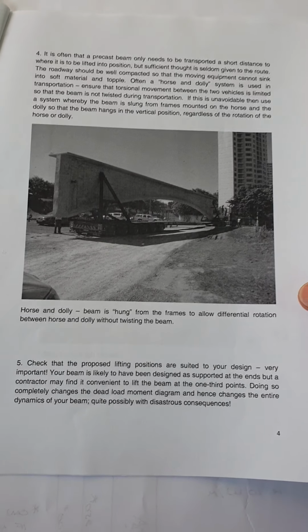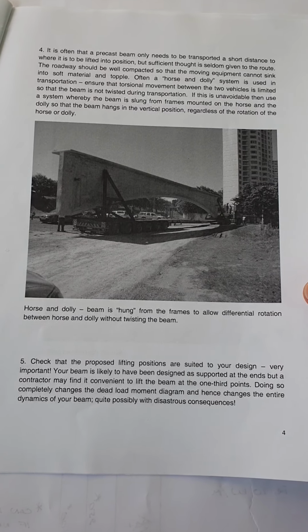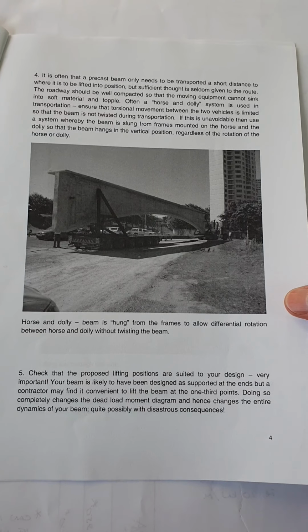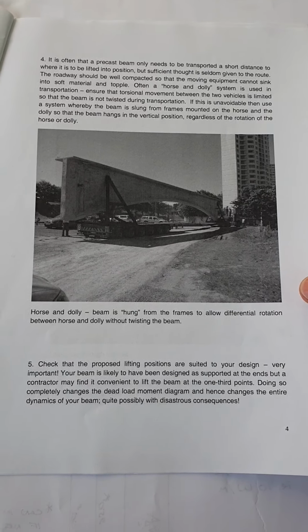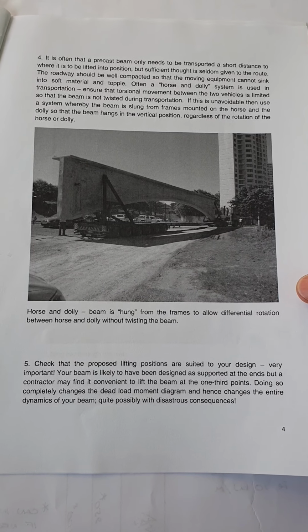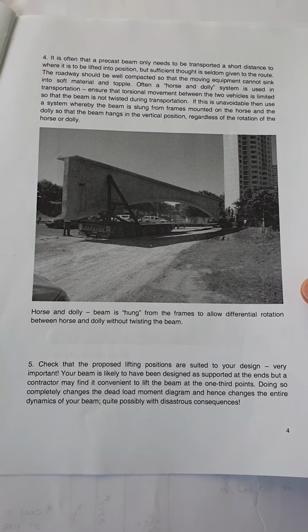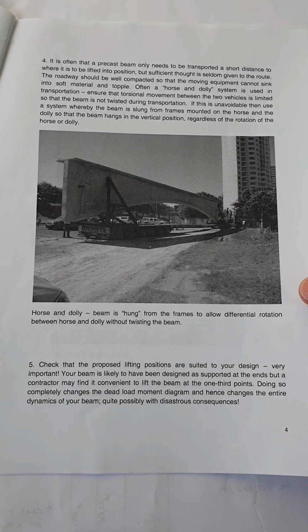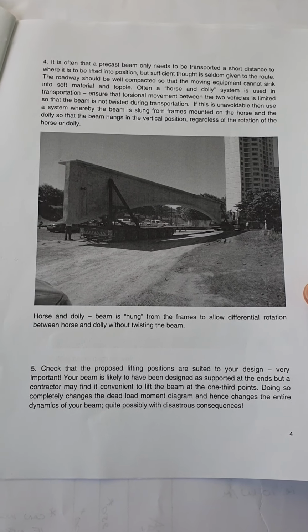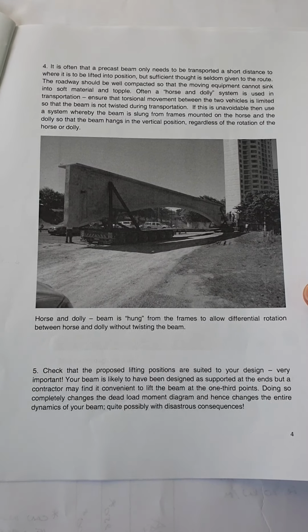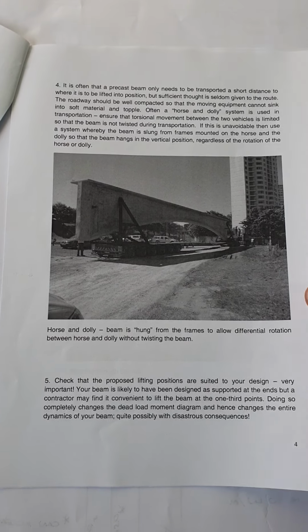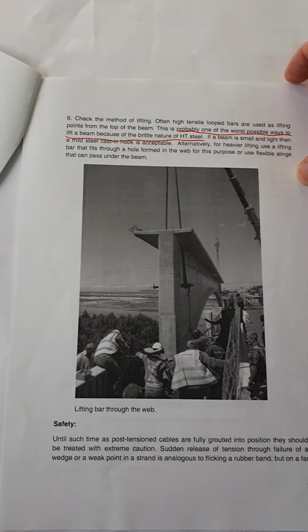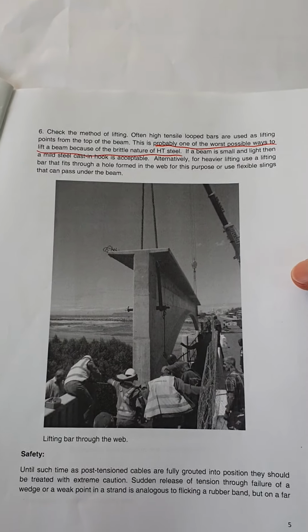Then point number 5, make sure that your lifting positions are suited to your design. Very important. Usually your beam is designed to be resting at the ends, and then if they lift with a crane from a point too far in from the end, remember that you're changing your bending moment. Your dead load bending moment is changing completely by doing that. Be very careful of doing that. So you must lift as close to the ends as possible, as close to your bearing positions as possible. Okay, method of lifting, also very important, just something to bear in mind.